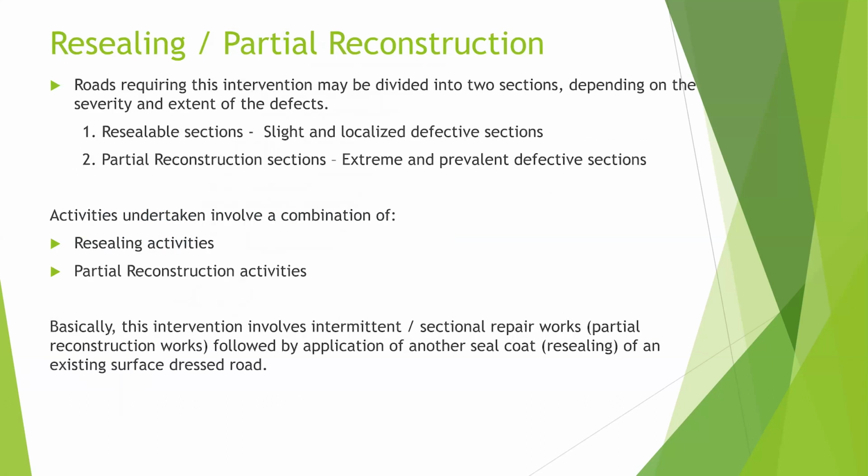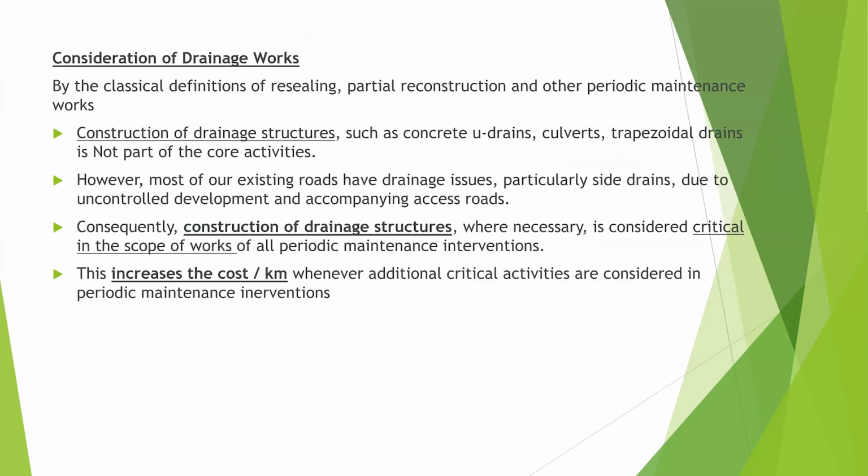So for resealing, resealable sections are where you have slight and localized defective sections. And for partial reconstruction, sections where you have extreme and prevalent defects. So like I said, sections of the road with slight and localized defects will have to be resealed, and extreme and prevalent defective sections would have to be reconstructed partially. Now, in all these two activities I have talked about, like I said, drainage is not part.